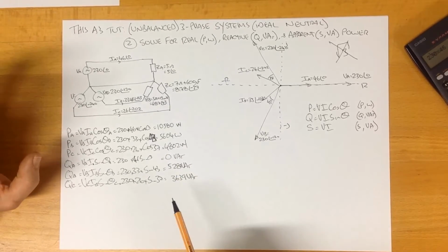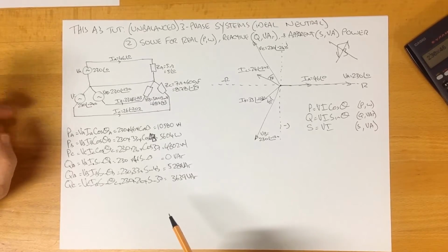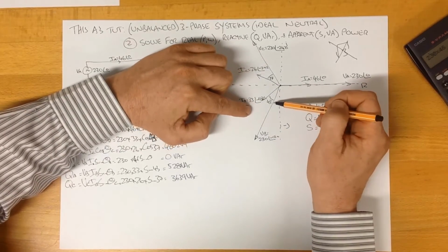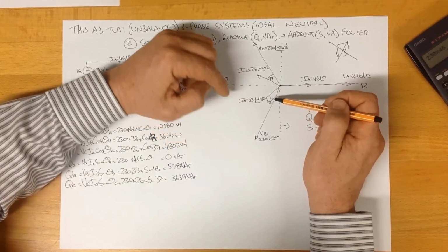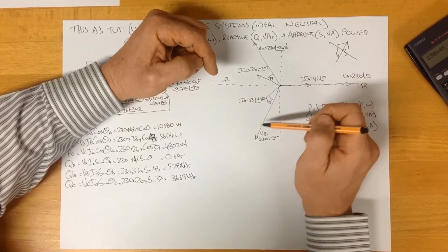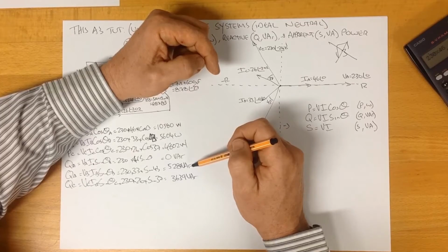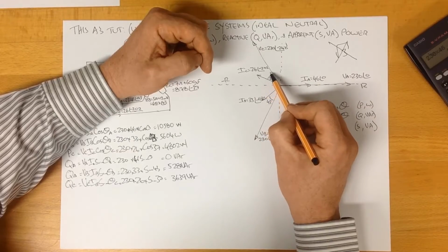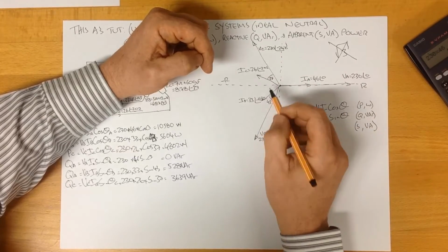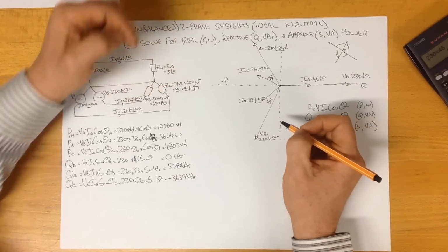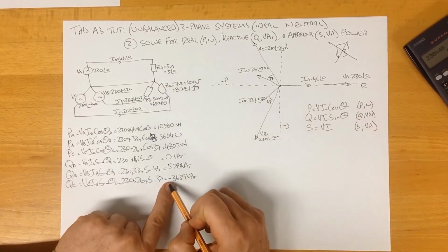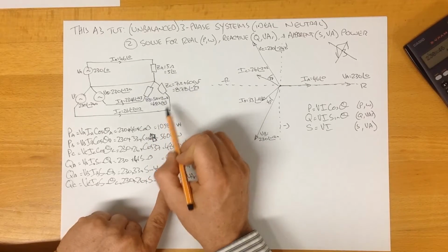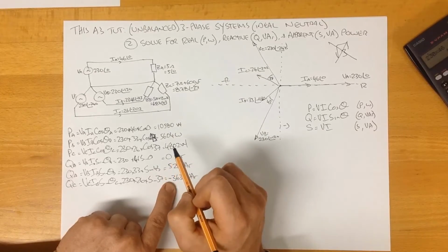Now, this is a point where, again, like I mentioned in the last tutorial, a lot of students start making very simple, very silly mistakes. Phase B was a reactive circuit, an inductive reactive circuit, with the current lagging the voltage. So our VARs are positive VARs. However, phase C is a capacitive circuit. The current leads our voltage. So that was often distinguished as being a minus. You need to know that the minus goes in here because of the capacitive in phase C. Your simple calculation won't show you that. You just need to know it and stick it in.